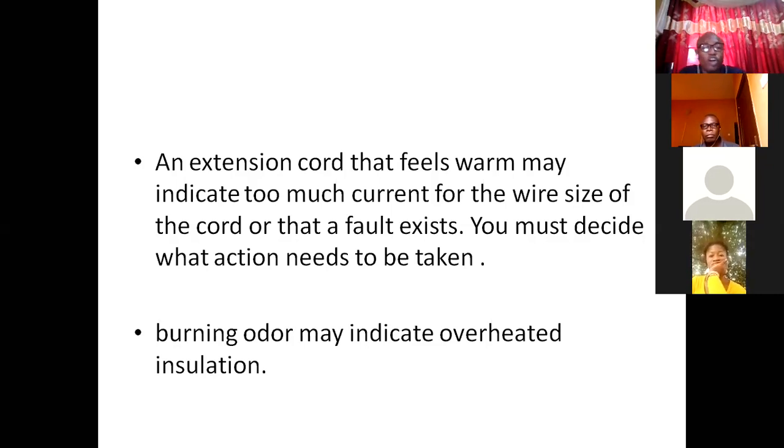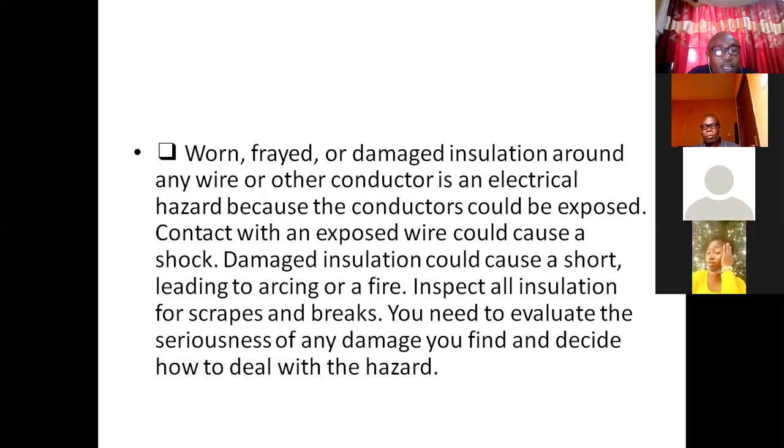When there is a burning odor in a place, it indicates that there is overheating of the insulation. That is also another way of evaluating a hazard. One, fried or damaged insulation around any wire or other conductor is an electrical hazard because the conductor can get exposed. Damaged insulation could also cause a short, leading to arc fire or cause fire in the house.